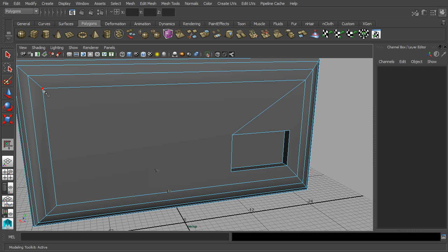What you want to do is just draw a line from one vertex to another. And it's kind of reading your mind as you get close to things. It's highlighting things. You want to select that vertex. Click it. And you don't hold the mouse down. You just go over to the other vertex and click it. And you get an orange line. That's a preview. If that's what you want, then press Enter. And it's actually executed.